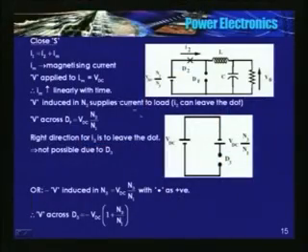But in the flyback there is no secondary current, whereas in the forward converter, when I close the switch, there is an equivalent current flowing in the secondary. Secondary current can flow because of the diode connection. I2 is finite, so there is I2 prime in the primary. So the voltage applied to the magnetizing inductance is VDC. So Im increases linearly with time.